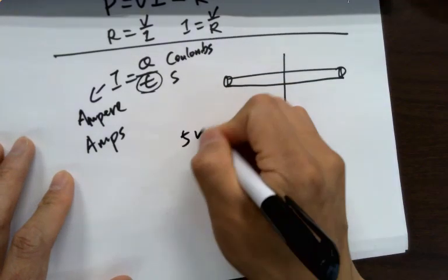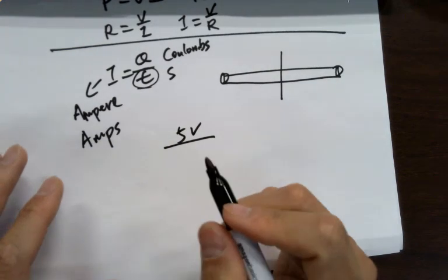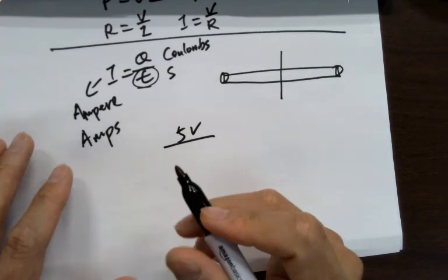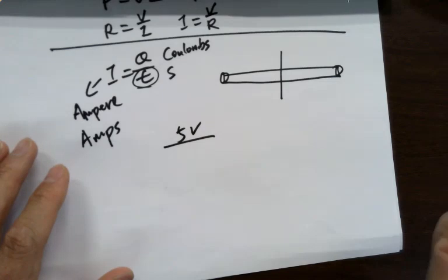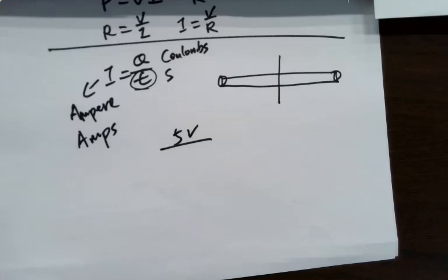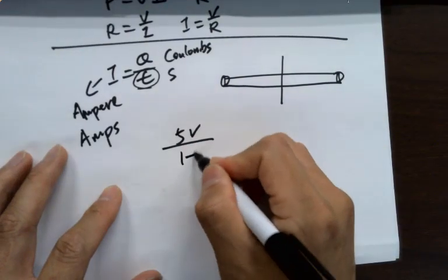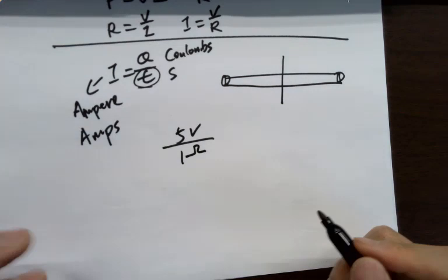If you take 5 volts, for example, we don't want to drain a lot of current from the circuits, so we use kilo ohms. But because all these are Circuit 1 problems, you are seeing a lot of bad values in there. It's just for calculations in the textbook. In real life, you will never see them. For example, if I do 5 volts and 1 ohm, who is going to do that?